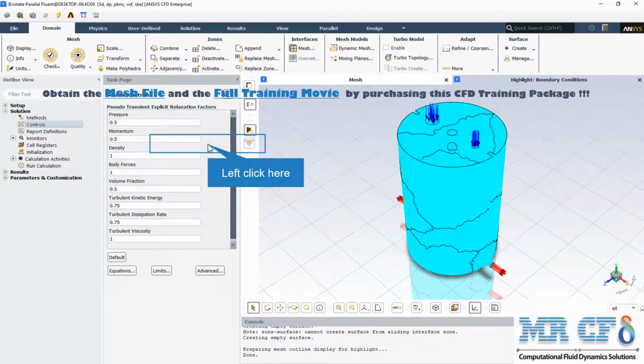These values are suitable for many problems, but for some particularly nonlinear problems, for example, some turbulent flows or high Rayleigh number natural convection problems, it is prudent to reduce the under relaxation factors initially. It is good practice to begin calculation using the default under relaxation factors. If the residuals continue to increase after the first 4 or 5 iterations, you should reduce the under relaxation factors.